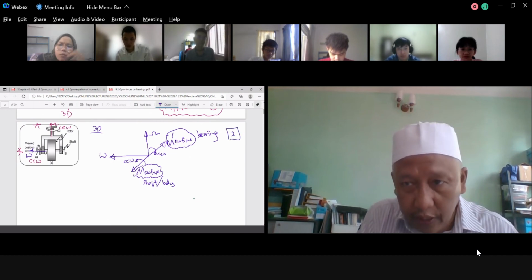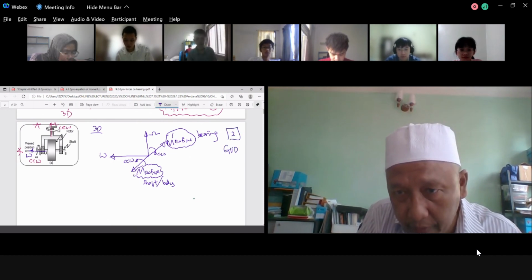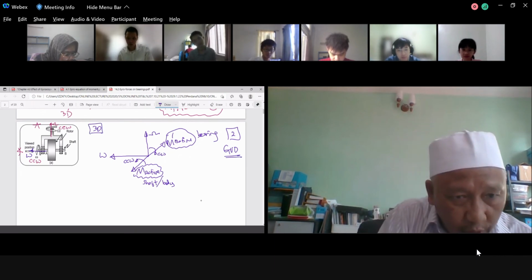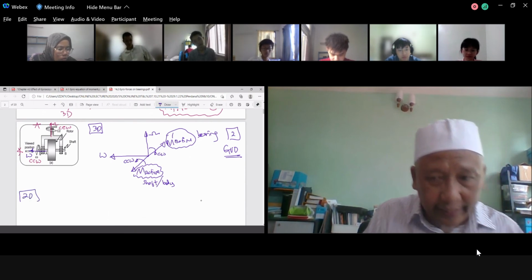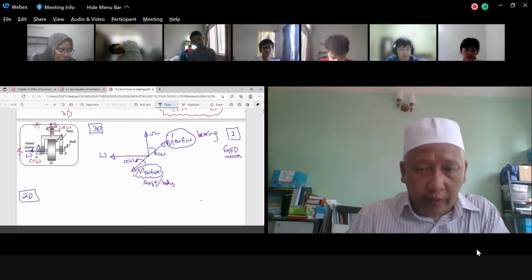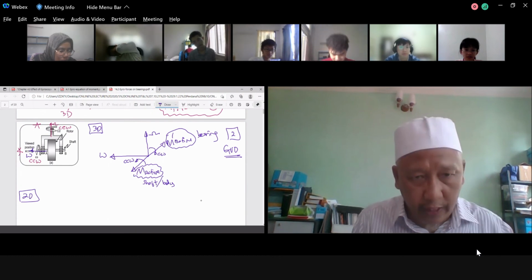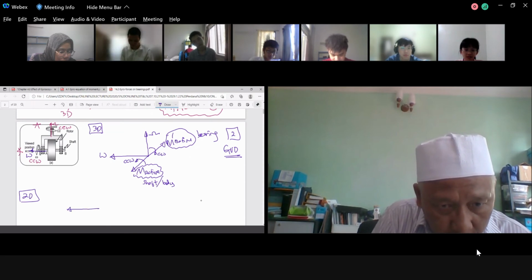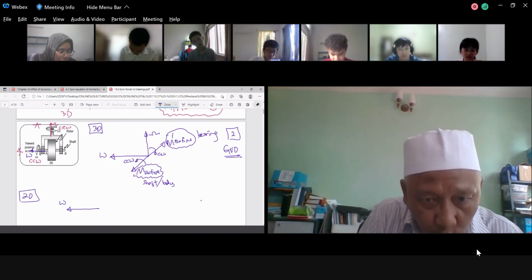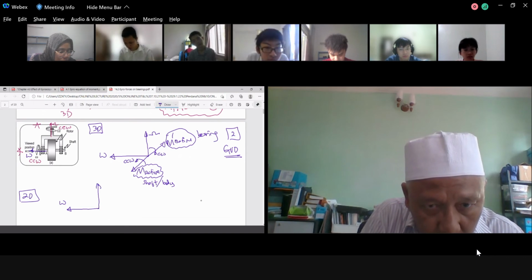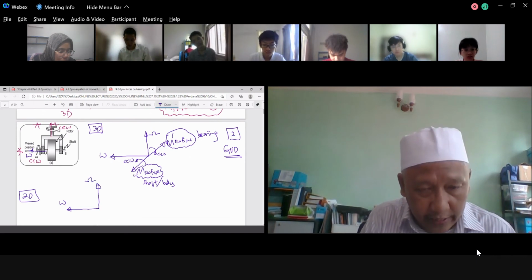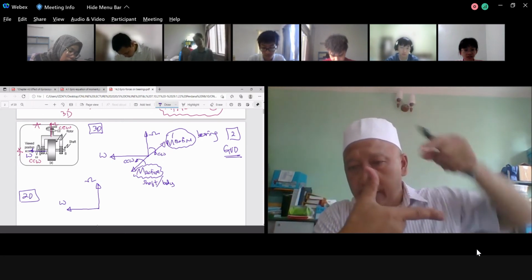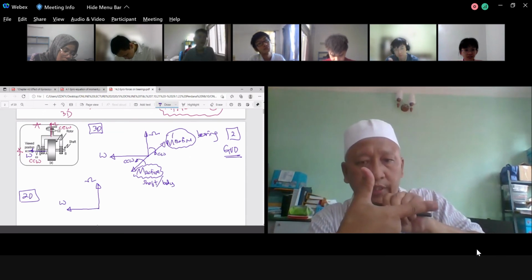So this one is number 2 just now. It's a gyroscopic vector diagram. This is 3D. What happens if you want to construct 2D? So let's construct 2D. But of course, in the exam or test, you do only one gyroscopic vector diagram, either 2D or 3D. So in 2D, this one has no changes, and this one also has no changes. Then the moment changes. You put your finger here. This one is the spin, and this is the precession. This one is the couple pointing to you. Am I correct or not?